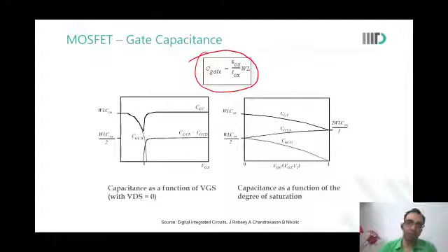The above graph shows the depletion region being formed, and therefore the change of charges happening at the boundary of the depletion region. And as soon as the inversion layer comes, independent of frequency, we at once have high capacitance.